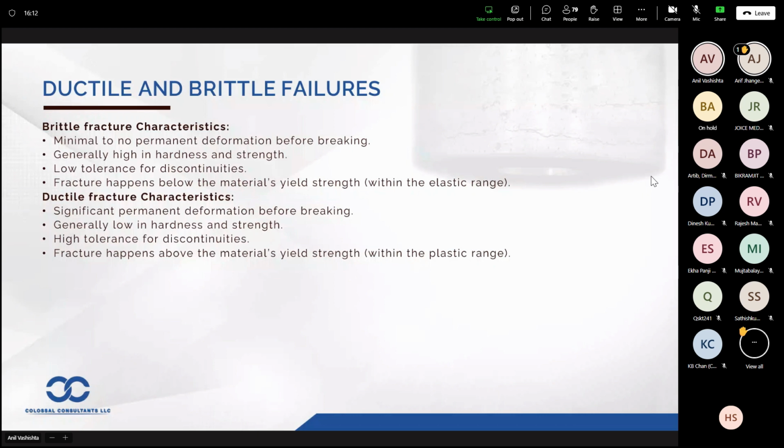Fatigue failure results in fracture from repetitive or fluctuating stresses below the material's tensile strength, and fracture progresses from tiny cracks due to fluctuating stresses. So there are 4 steps of progression. Step 1 is the repetitive low level loads induce submicroscopic changes in the metal structure.